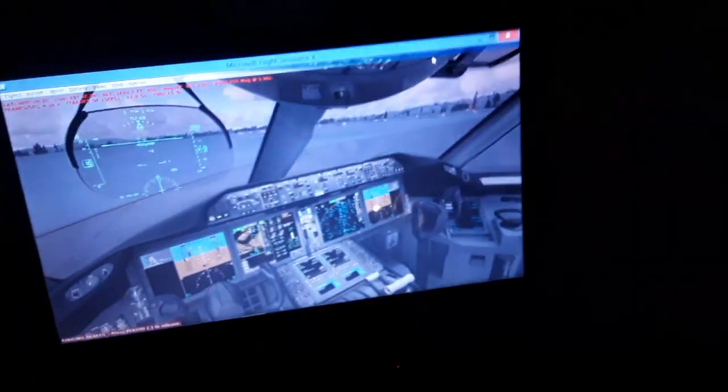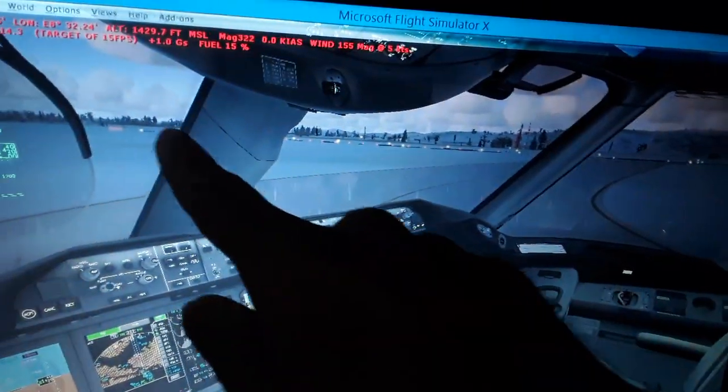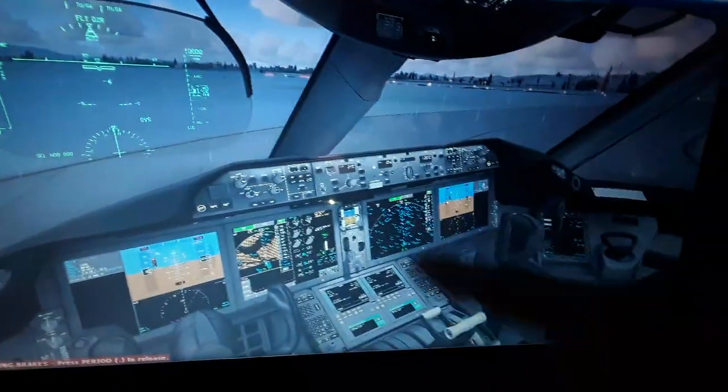Also we use 15 degrees of flaps for this flight. I'm gonna use the runway data. So we have the runway here. We're gonna use for this flight the runway 14 in the Zurich International Airport. You can see the runway length over here, the threshold and the length. So we have the runway. We're gonna set it in the flight management computer here. The runway length, the runway slope, the wind direction, the speed, the barometric pressure, the density of the air, and the temperature of the air.